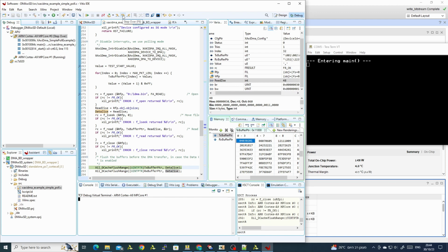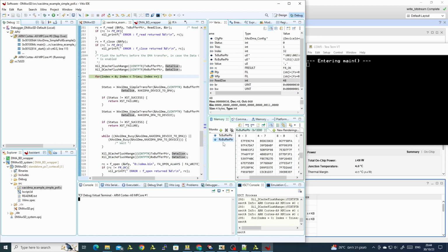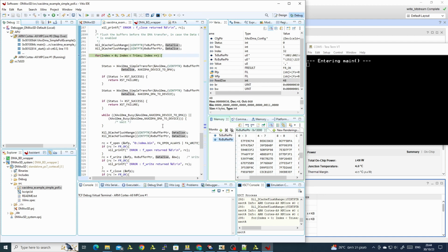We'll flush the cache, so we transfer actually from the cache to the DDR, so the DMA can work on it. We fetch the RX as well, but there's nothing there. And now we can work the DDR. Now if you remember, the DDR have the weight here, the configuration and so on, so we just skip to that until we have the DMA finish writing.